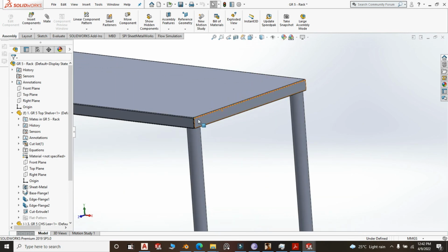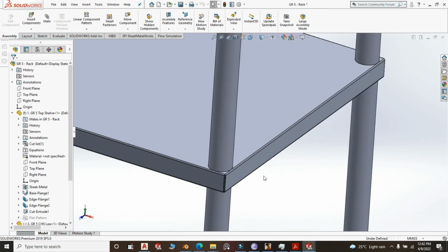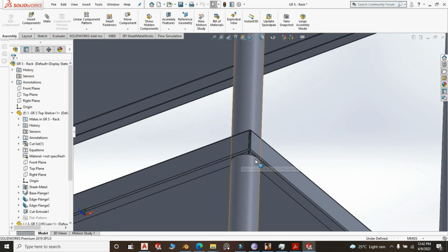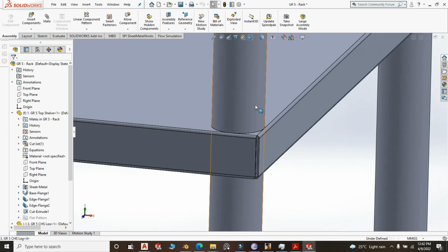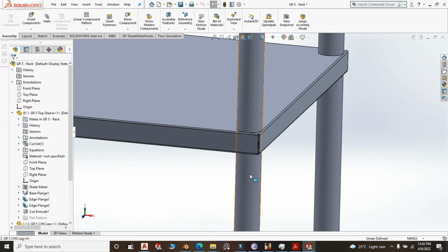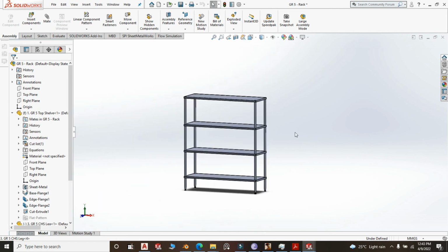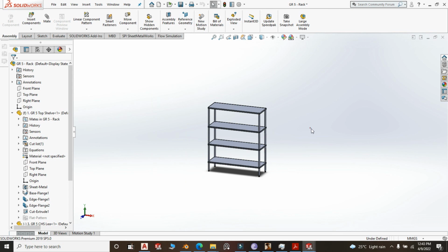Fine. Now you see, with this rack you will do welding here, and under the top doesn't change. Now as opposed to the shelf, you will do welding here, and welding here. Then you will polish here, and as you're polishing, it is very easy to touch these parts with the tool, because you are trying to polish this with a straight grinder, and it is not a small thing. The grinder is huge, easy to touch this, then you might find yourself ending up polishing the entire legs, okay? But if you are an expert, go ahead. At least this looks clean. Whatever you choose, go ahead.